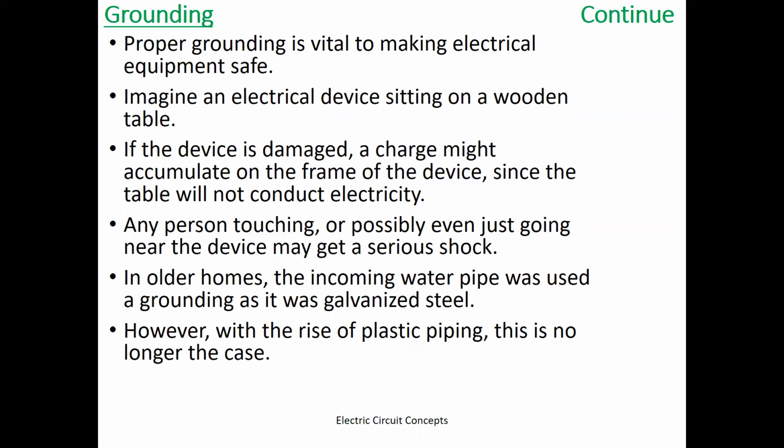Imagine an electrical device sitting on a wooden table. If the device is damaged, a charge might accumulate on the frame of the device, since the table will not conduct electricity. Any person touching or possibly even just going near the device may get a serious shock. In older homes, the incoming water pipe was used as a ground as it was galvanized steel. However, with the rise of plastic pipes, this is no longer the case.